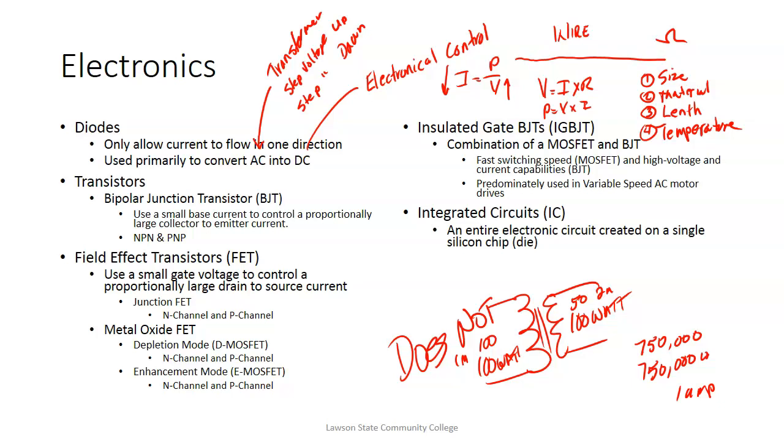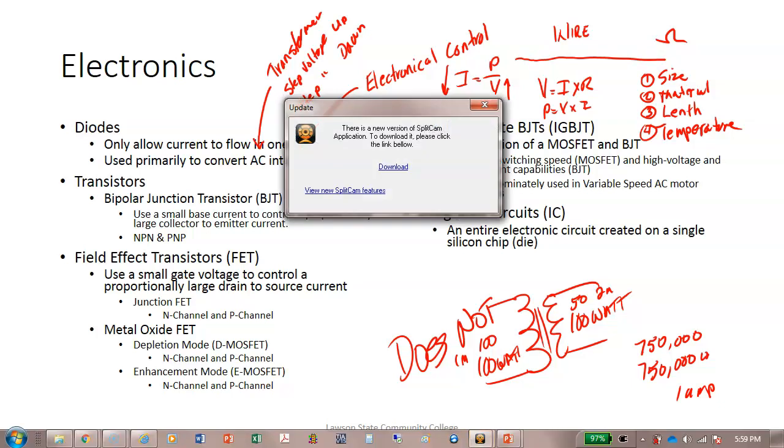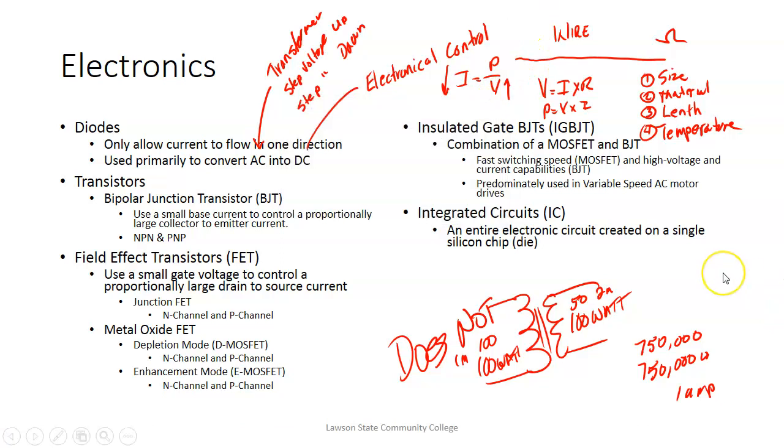But you would notice the gauge of the wires get bigger as the voltage, because we're dealing with the resistance. So yeah, but it allows the power company to use aluminum, even though aluminum is a good conductor. It's not the best conductor. It allows them to use aluminum on these really high voltage lines, and it also allows them to use smaller gauges. Aluminum is lighter, aluminum is cheaper. So all your high voltage lines are going to be aluminum. And then your low voltage lines are going to start moving toward copper. So that's the reason, that's the big advantage of AC.